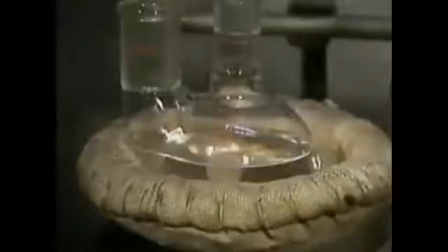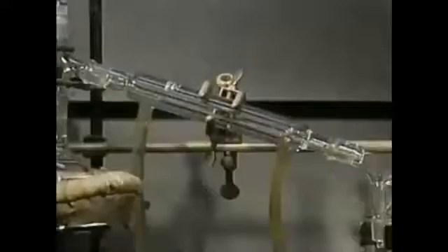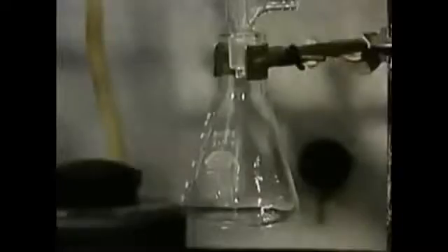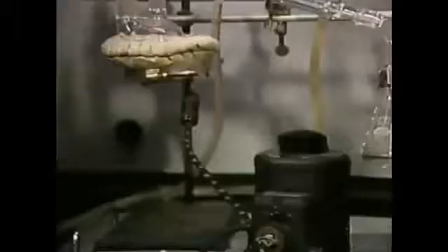In this part, we're going to look at how a binary liquid mixture, that is, a mixture that has two components, can be separated into a lighter component and a heavier component. We've set up a laboratory demonstration to do this. In order to separate the components of a liquid mixture, a distillation system must have a container for the liquid mixture, a condenser. This one consists of an inner tube for the vapors and an outer tube with cooling water running through it, a receiver to collect the liquid leaving the condenser, and a source of heat. We'll use an electric heater.